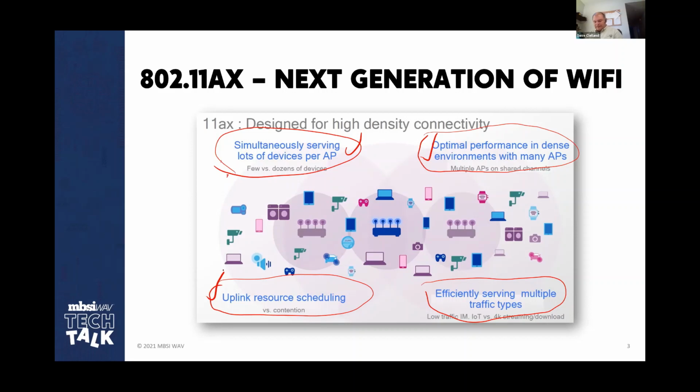This is like in access networks: when a subscriber module has something to say, it will say it in the uplink interval, and the access point will speak to the CPE devices or subscriber modules, whatever you want to call them, in the downlink interval of TDD, a time division duplex protocol.